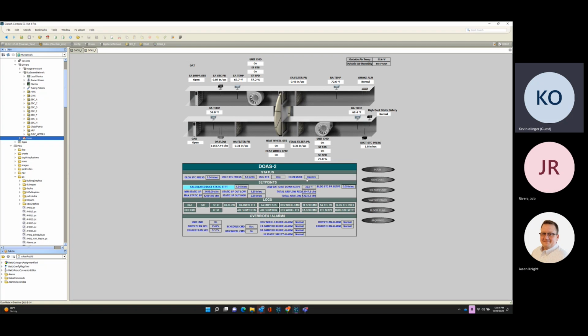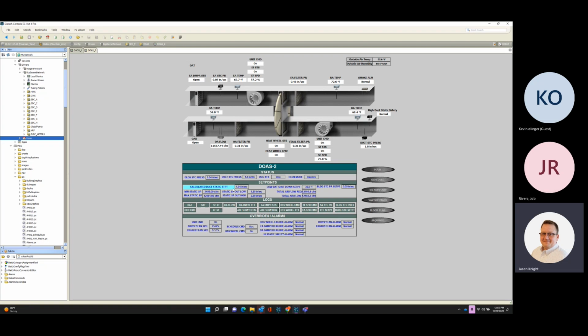And then can I go back to the duct static pressure reference or set point that you're driving to maintain the volume? It's really small on our screen, so we can't really see it. I'm assuming there's a minimum duct static that it's going to maintain no matter what the conditions are, correct? Yeah, that would be your static set point out low. So the lowest it'll ever let it drive it is 1.25 inches.